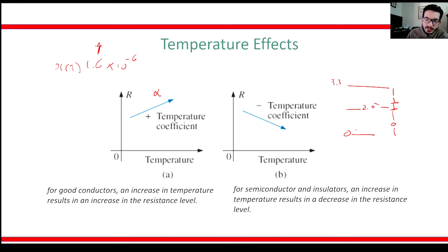The voltage threshold is fixed, but if the resistance changed, now it's going to have errors because it's not going to be 2.5. It's going to have a different voltage applied, even though it's expecting a 2.5, as it was at normal temperature conditions.